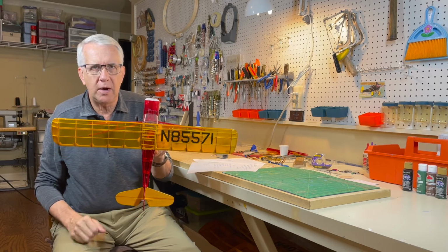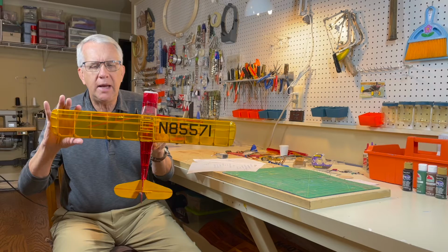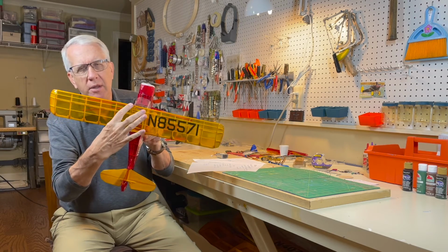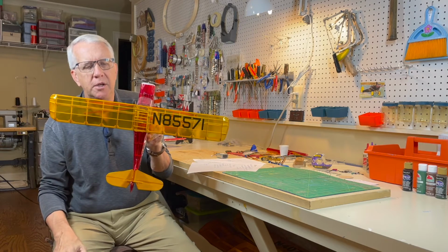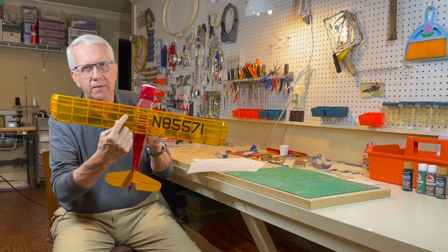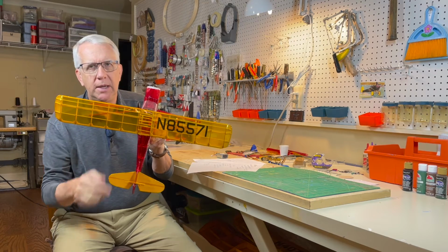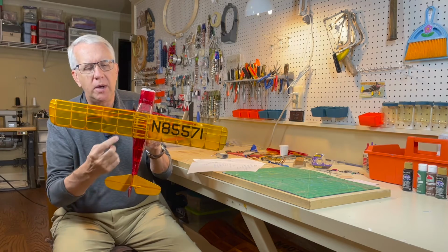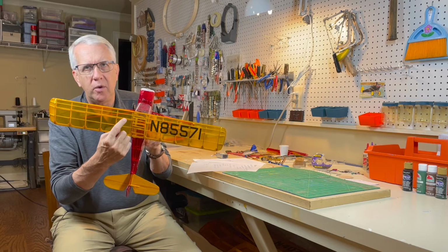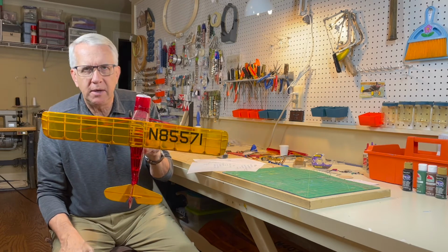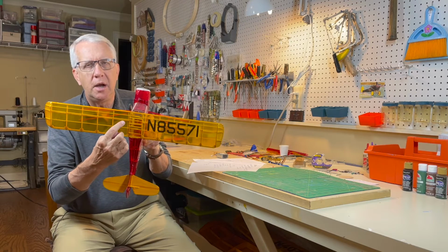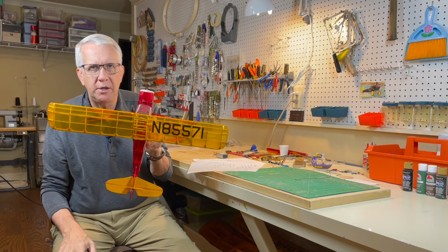So to find the center of gravity for a straight wing airplane, just measure the distance from the leading edge to the trailing edge. Let's call this 4 inches for the purposes of discussion. The center of gravity is between 20% back to 25% back from the leading edge, 25% of 4 inches being 1 inch. So you literally measure 1 inch back, or a little bit forward. That would be your center of gravity range. I would just split the difference, about 22% of the distance back from the leading edge to the trailing edge. That is your center of gravity location.